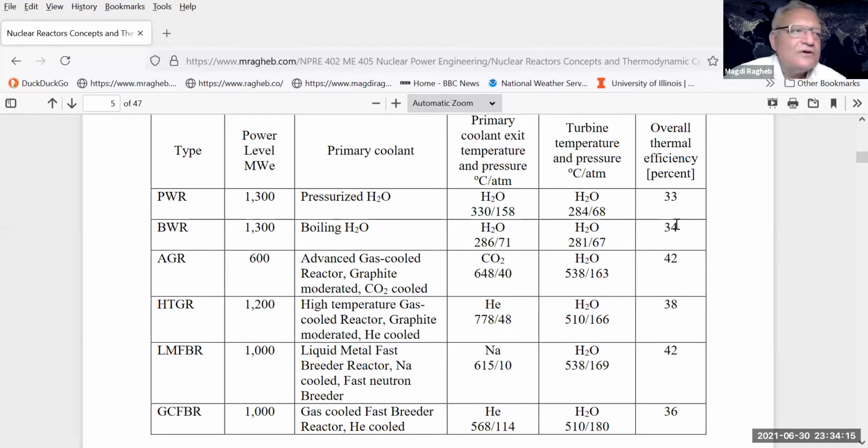or 1/3. So 2/3 of the energy in that particular design has to be dedicated to establishing what we call the flow systems. Not that we really have to throw energy to the environment. It's part of the design that we have to dedicate 2/3 of the energy to establish the flow from the high temperature reservoir to the low temperature reservoir.